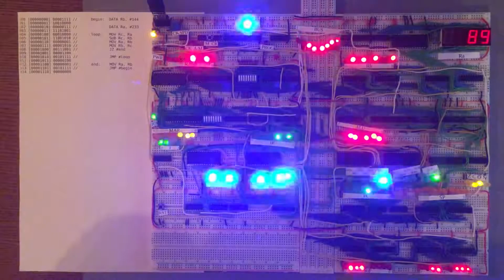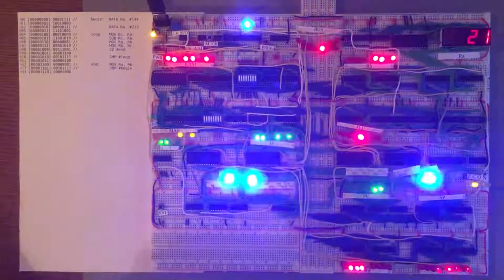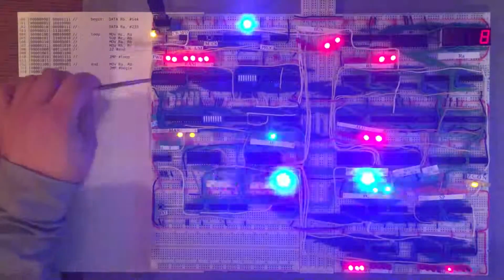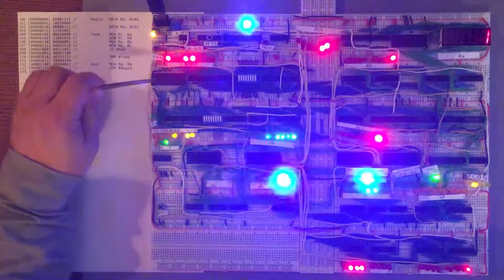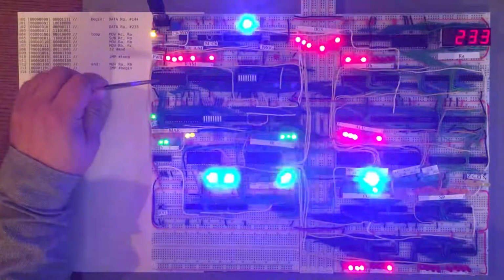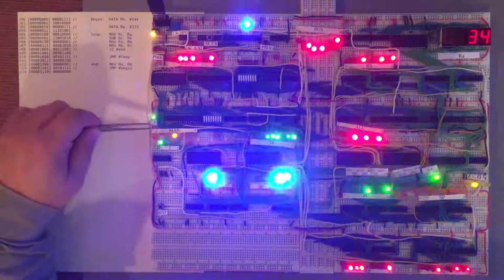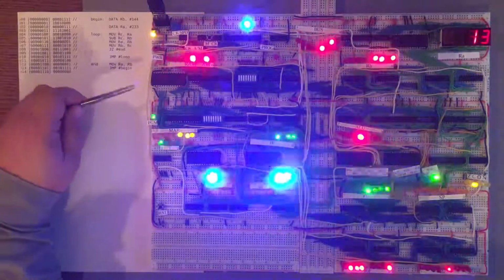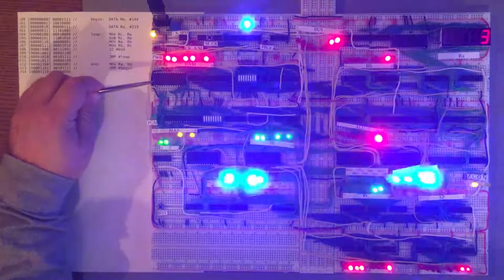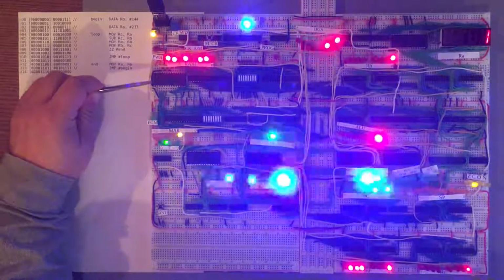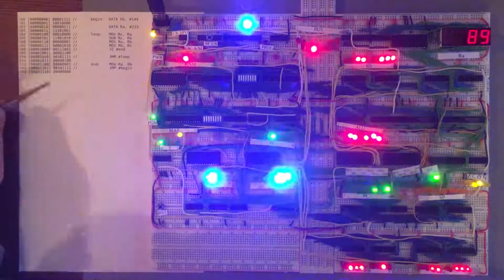Now, what I intend to do in the next episode is have a closer look at our memory, at our RAM, random access memory. And so that's located over here. This is the actual RAM chip. And as I explained in the introduction, we're using, let's say, a Harvard-inspired architecture where we're using 2 RAMs, or we're splitting our RAM in 2. So we have a part which we use for data and for the stack, and we have a separate part which we're using to contain the program.